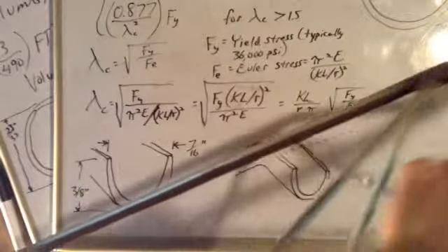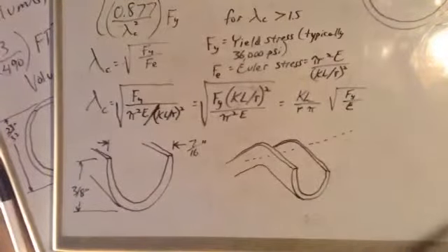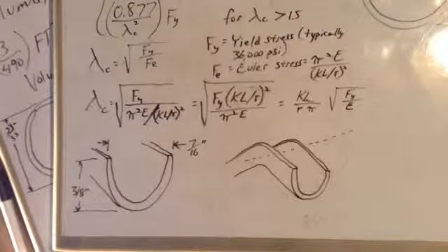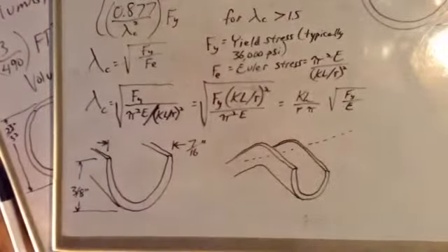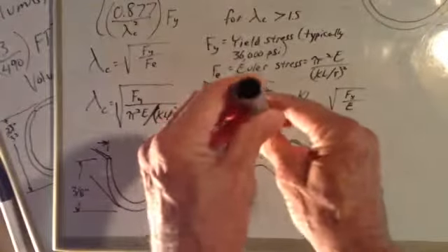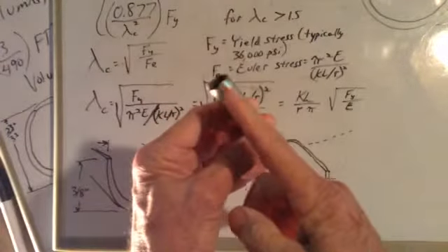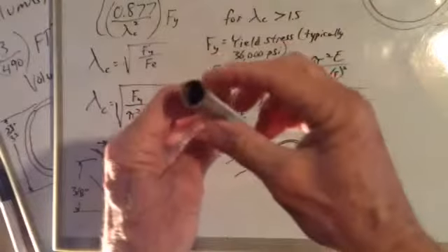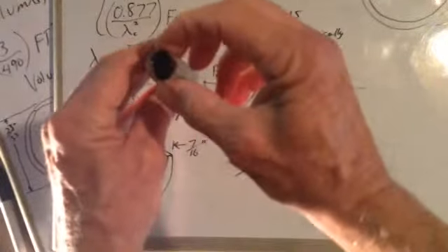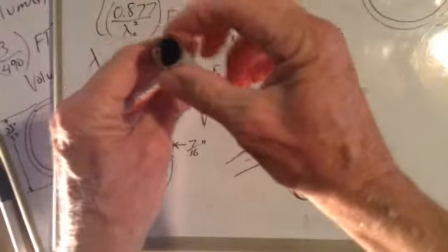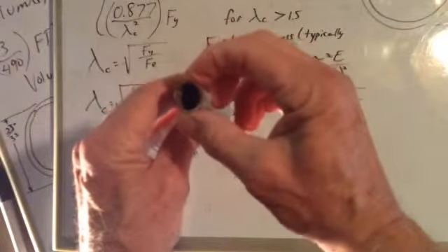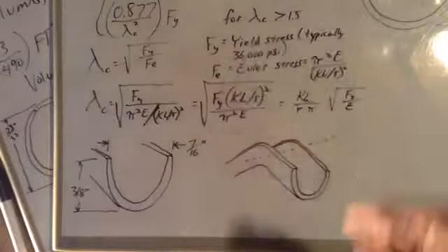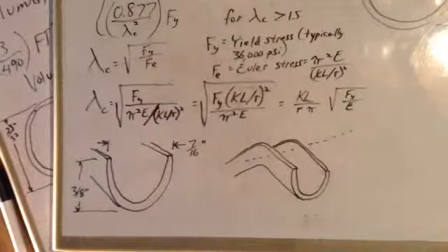So it was cut out of a piece of 1/2 inch electrical conduit. Here's a sample of that right here. This was ripped in half with a metal cutting blade on a circular saw, and then one of the U pieces that was left was squeezed down to about 1/4 of an inch wide on a 1/4 inch piece of steel. So that's how that came about.